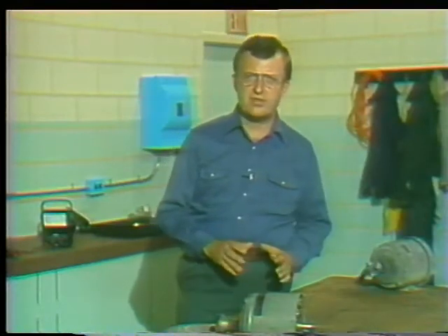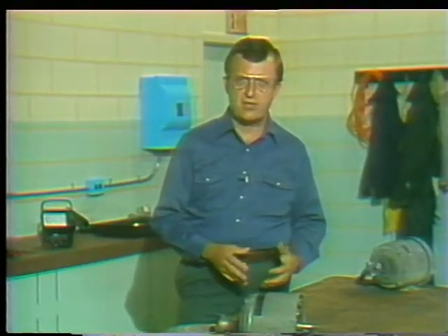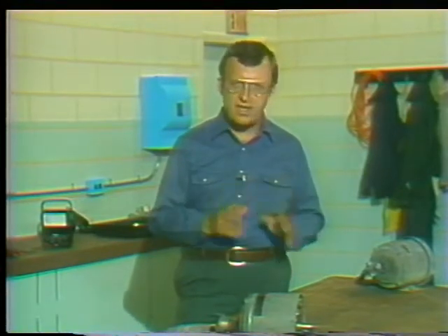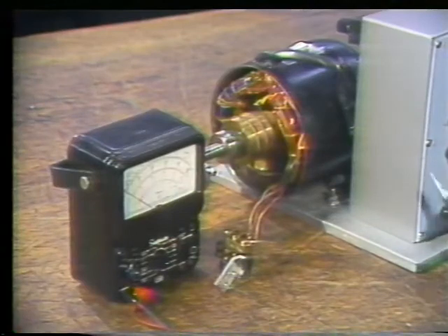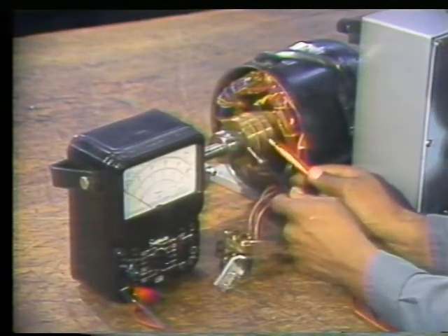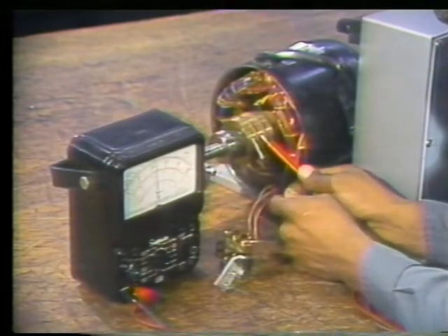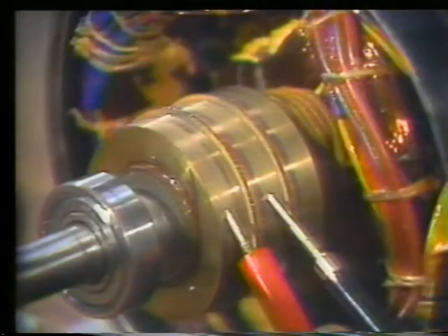But if you did find a ground, you could locate it by following the wiring or by separation of the circuit into smaller parts and testing each part until the ground is located. Now, after checking for grounds, the next step is to test for opens. You use a multimeter for this test, and remember, you still need to test the rotor and the external resistances separately. Test the slip rings two at a time to measure the resistance through the coils. This is similar to testing for opens in the stator. Test the first and second slip rings.